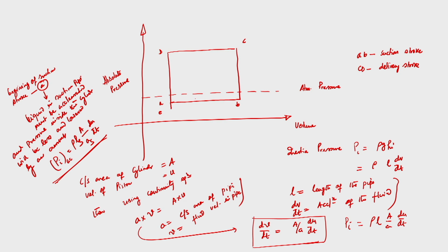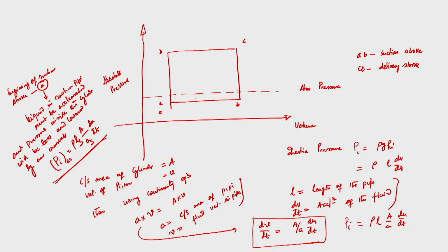Similarly, at the end of the suction stroke, the liquid in the suction pipeline will be decelerated, because the suction valve will close, and the pressure inside the cylinder must be increased by an equal amount, rho Ls A by As du dt. So now that will be increased.